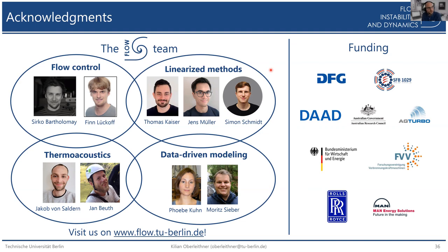What we want to do is assimilate a RANS solution onto the mean fields we got from accurate mean field prediction, let's say LES or experiments. We want to assimilate a RANS solution with a simple eddy viscosity model onto the data, and then we take this eddy viscosity for our linearized analysis.